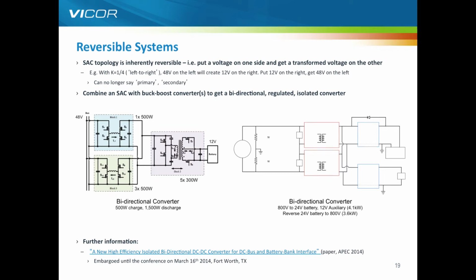But also, if you are operating your bulldozer or your digger in the desert and you want to stop for lunch, then you want to turn off the diesel engine and save fuel. But you still want your air conditioner to run. So at that point, the battery goes and using the bypass diode in this case, because we don't need tight regulation for this kind of load, creates back to that 700 or 800 volt rail to run the air conditioner. So another example of stacking and also reversibility using these two building blocks.